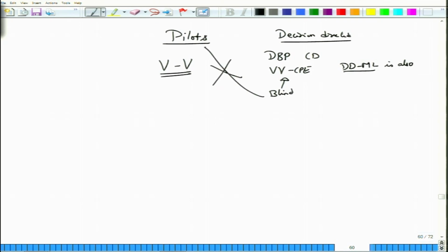The idea of this one is very simple. First, assume that there is no noise. So, you have s_k e^{j phi_k}. Please note that I am not writing this p here, because I do not need to know the pilot here. There is nothing I need to know, except that I need to have a constellation of the form M-ary PSK, of which the simplest one is QPSK. You could either have symbols arranged at 45 degrees and differences of 90 degrees that way, or you can have these symbols, the ones shown in blue, but nevertheless all of these fall on the same circle. Although I have not shown you the correct circle, they all fall on the same circle, which means they all have the same magnitude.